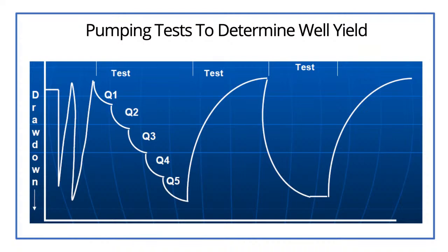And we're going to pump that down till we basically get a period of steady state conditions where the drawdown stabilizes for the pumping rate we have. So basically you get a flat line on your drawdown. And then we measure that for a period of time. For instance, in California, depending on the length of your test, we want a 2 to 4 hour period where you have steady state conditions. And usually 4 hours is what we're looking for, to show that this drawdown is stable at this pumping rate.